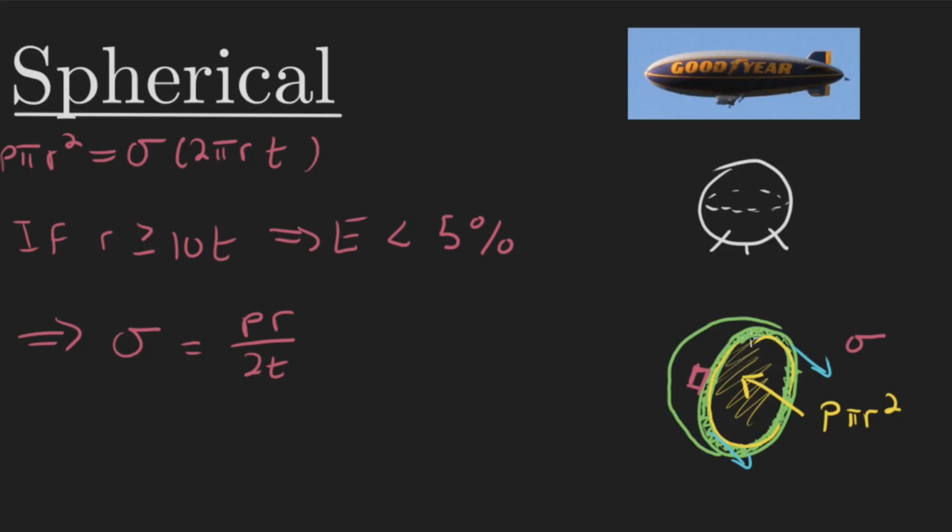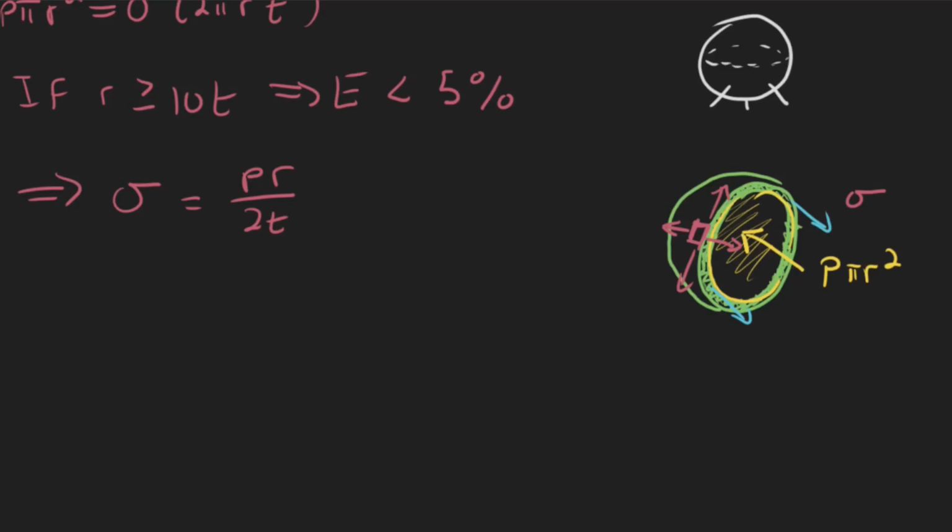Because you can imagine I could do this around this axis right here, or around this axis right here, or really any axis where I'm splitting it in half. So we're going to have this pressure. This would be related to this side right here and right here, but I'd also have an equal pressure if I did an analysis where I split it across this line. I'd have an equal pressure right here, and all of that is normal, and I would have no shear. So if you remember, a state where we have all normal and no shear stress is the maximum or the principal, right? So if I go ahead and graph this, this right here is my shear, and this is my normal stress. So this is my sigma axis, tau axis, right?